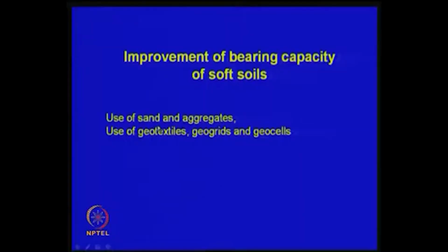That is an assumption that one should normally make, but if you are using sand and aggregates, it is fine. Sand and aggregate are actually required. You can't walk on the soft soil, you have to put some load of sand and aggregate, then only you can do something, because as I just mentioned, they distribute the loads, right. So when you are putting sand and aggregate, why do you not put geotextiles, geogrids and geocells there? That is an obvious question. So we do that here, and we have a couple of ways of doing it.